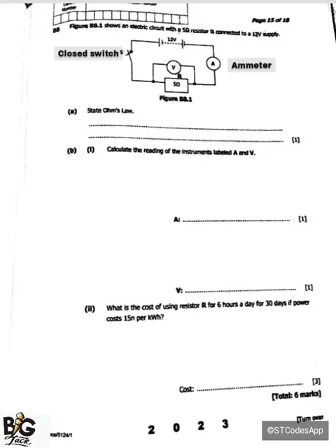and the voltage on the circuit diagram is 12 volts. Then the resistance on the diagram is 5 ohms. So I'm going to say current is equal to 12 volts divided by 5 ohms. Then the answer is going to be 2.4 amps. Like the way I was saying, current is measured in amps or amperes. So I'm going to put capital letter A to denote the amps or amperes.